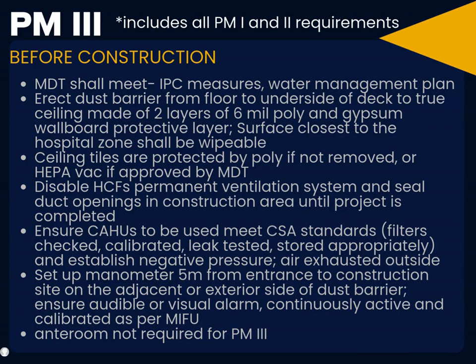Surfaces closest to the patient zone must be wipeable. Modular wall panels or temporary containment vessels can be used if approved by the MDT. The facility's permanent ventilation system in the construction area is turned off and all duct openings are sealed until the project is finished. The construction air handling unit, CAHU, used must meet CSA standards, exhaust air directly outside away from intake vents, and filter air through a HEPA filter.